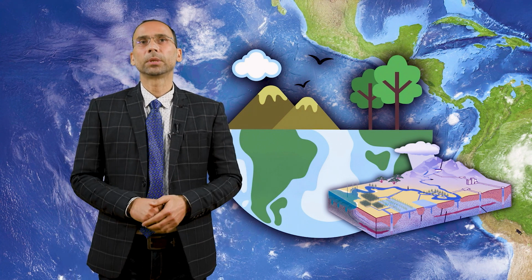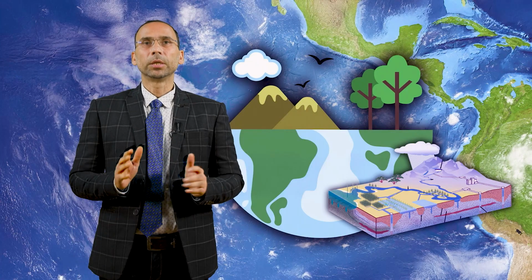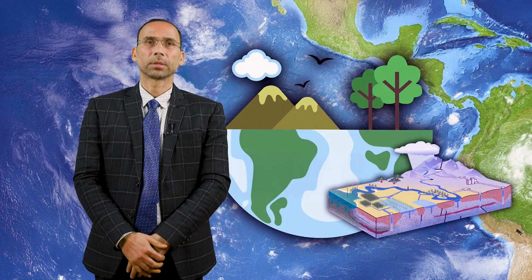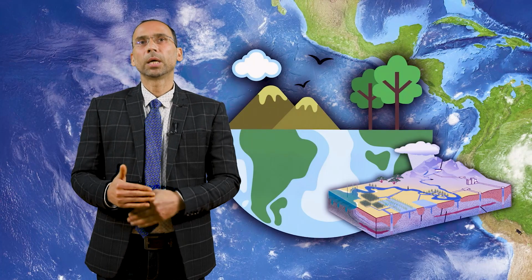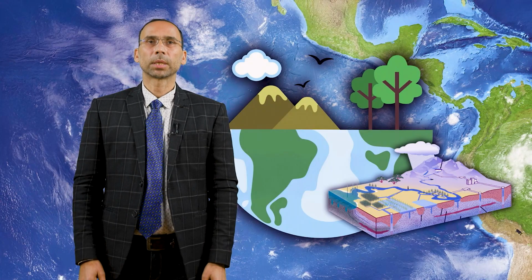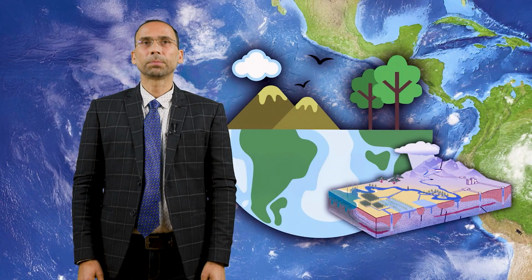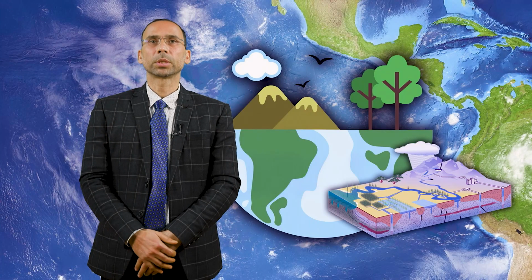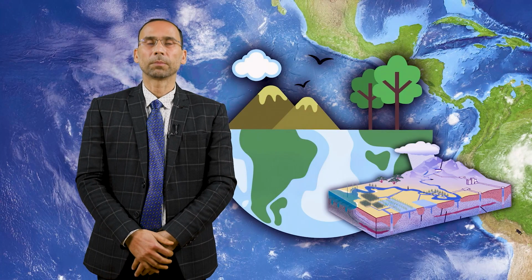The radioactive isotopes like tritium, carbon-14 and krypton-81 determine the age of water and measure recharge rates. Isotope studies in the Himalayan catchments have shown that meltwater is sometimes 30 to 40% of the total river flow and 44 to 68% of the groundwater.